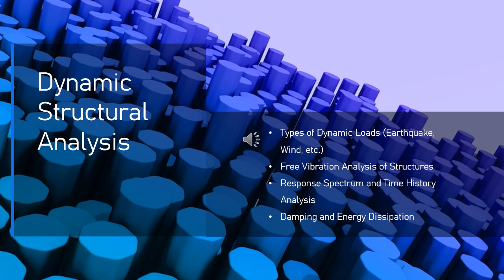Wind load analysis. RSA can be used for analyzing structures subjected to dynamic wind forces, especially for tall buildings and towers. Efficiency. RSA is often used for preliminary design stages or when a quick assessment is needed without requiring a full time history analysis. Limitations of response spectrum analysis.